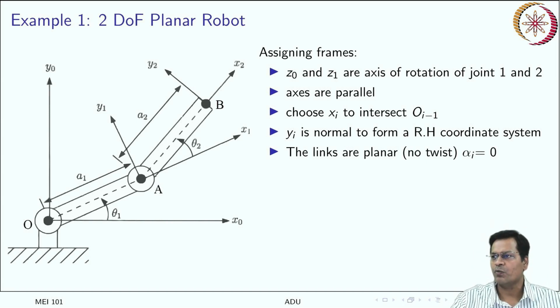So what I actually want to do here, I want to place the frame 0. I want to place every link with a frame, and I want to find out the transformation matrices, link transformation matrices, so that I can do concatenation, and finally I can reach till the end effector. Got it? So let me see if I can explain it well using this figure.